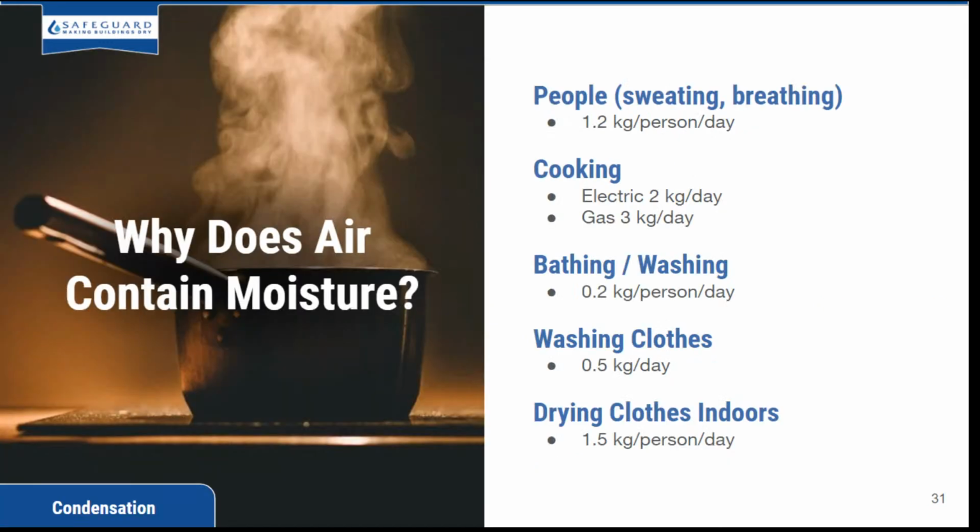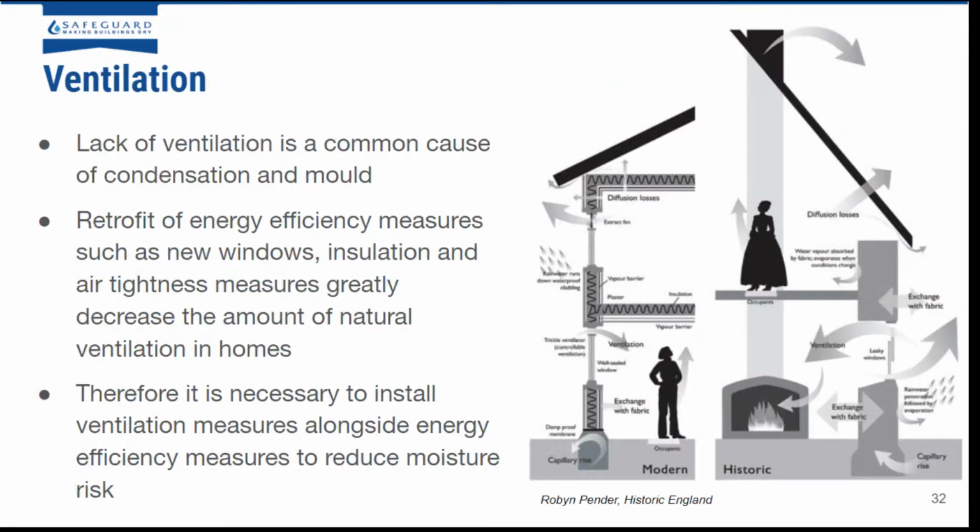So why does our air contain moisture? Basically just by people existing create moisture, and it's a very natural thing for people to do, like sweating and breathing create moisture, cooking, bathing, washing clothes and drying clothes indoors. All normal things that people will do will generate moisture inside the house. So ventilation really is key. So lack of ventilation is a common cause of condensation and mould.